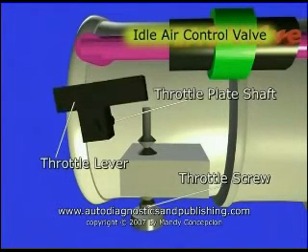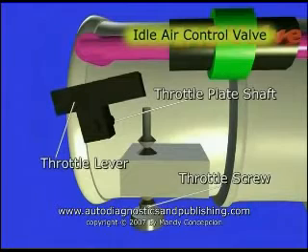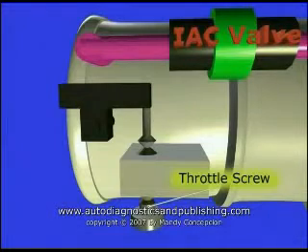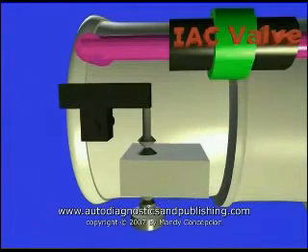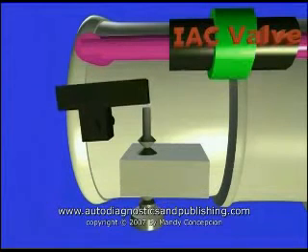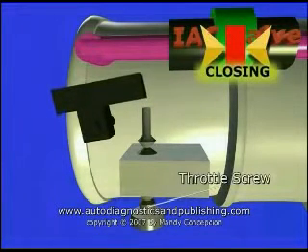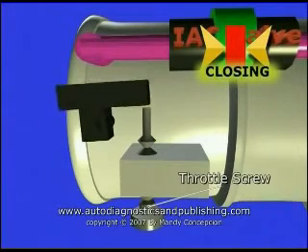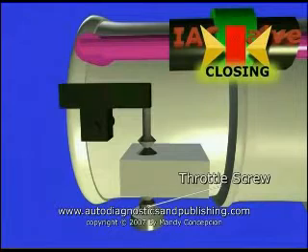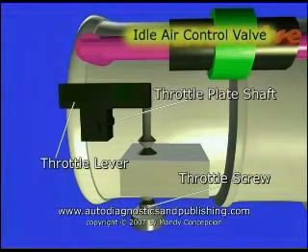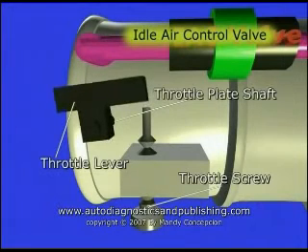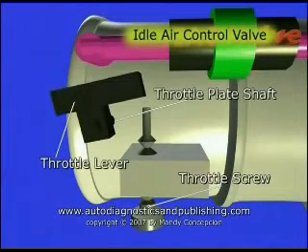Seen here, the minimum air rate adjustment is closely linked to the throttle plates and its adjustment. Notice the adjustment screw that controls the small opening of the throttle plates. By simply closing or plugging the idle control valve, adjusting the throttle screw for a minimum idle speed, and then readjusting the TPS, the desired idle condition can always be met by the engine computer. If the TPS is not adjustable, then simply verify the closed idle value to proper manufacturer's specifications after the minimum air rate adjustment is done.